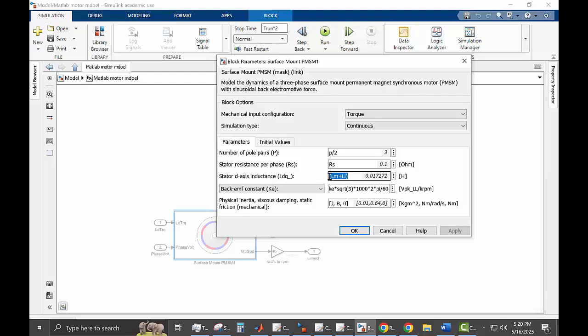When we do our advanced electric drive course, we will again use Professor Mohan's way of deriving the equations, which has power invariance. So there the LM that we calculate in the DQ will be completely different from the LM we have in our per phase model. So this again is a point of common confusion with a lot of people. But the way MATLAB does the DQ modeling, LM is the same as the LM in DQ as well as in the per phase model.